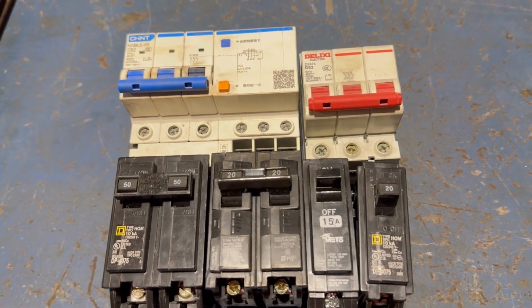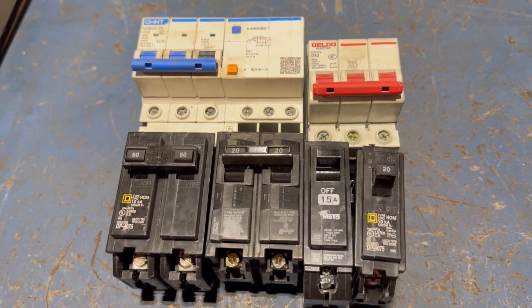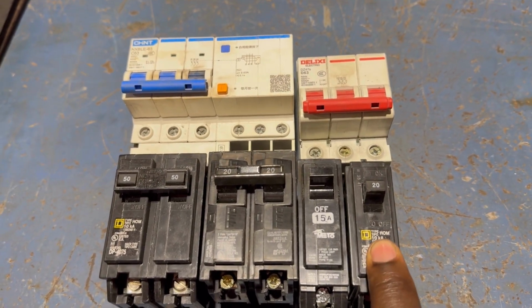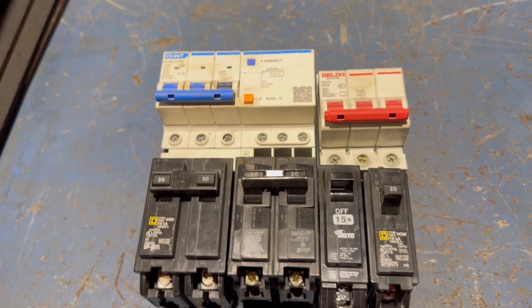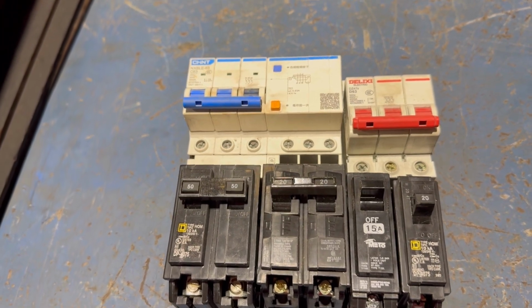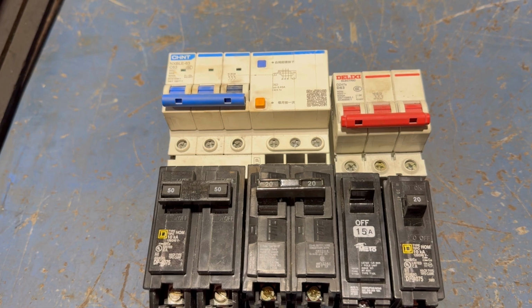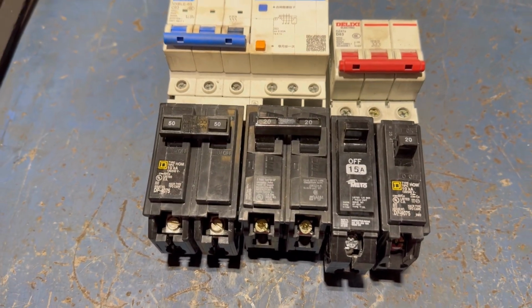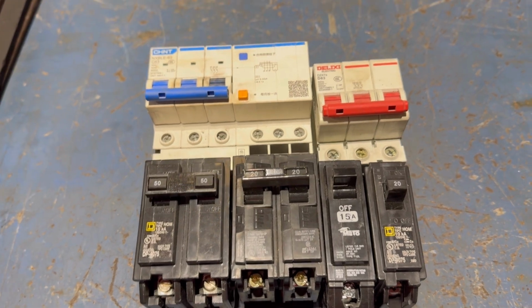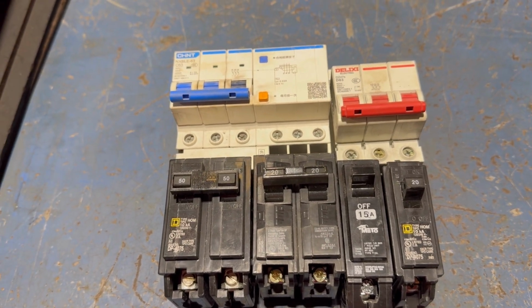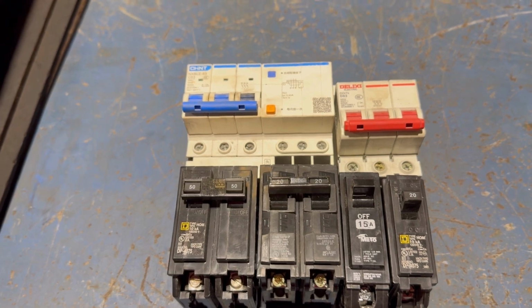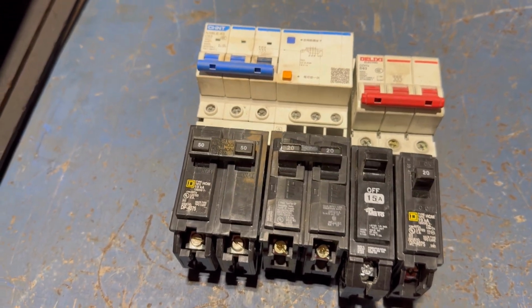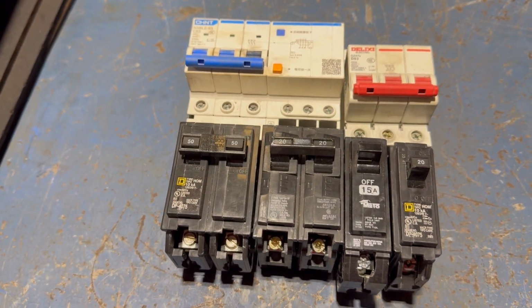So the motor is 10 amps, so you can safely protect it with a 20 amp breaker. But guess what? On starting, the motor current rises to 3 times the rated current. So even though the motor is rated at 10 amps, on starting, the motor pulls a current of 30 amps. But it does that just on starting, for literally a few seconds or a few milliseconds, and then it goes back down to its rated current.